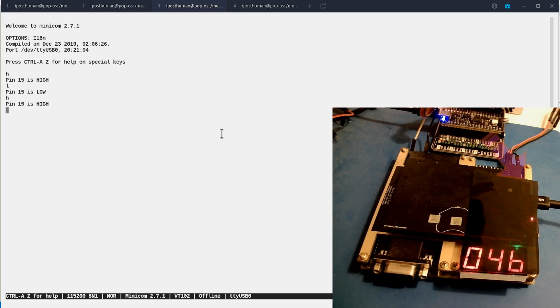And I'll do that again, only I'll do it slower. I'll just hit L, and so it's back low, and now it's high. And it briefly flickers because remember through that code we were talking about, it's actually setting and then unsetting. So now with it high, I'll hit the T key, and that'll just keep clocking it.